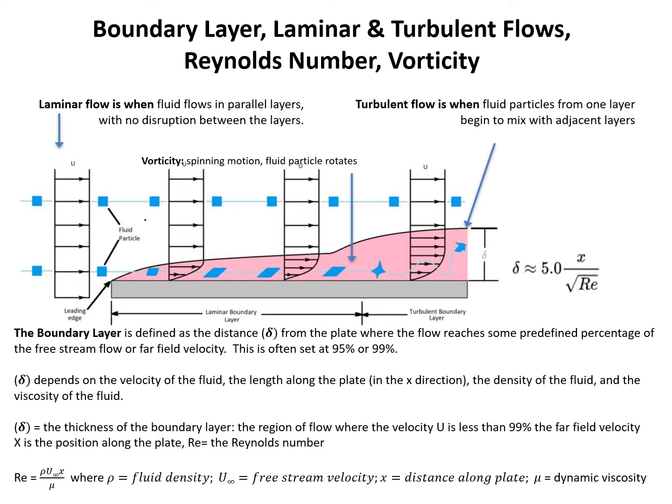This boundary layer depends on the distance you are along the plate, but it also depends on the viscosity of the fluid, and that's not surprising because the shear stress is basically the change in velocity with respect to the distance you are away from the plate, and the relationship with the stress that's applied is the definition of viscosity.